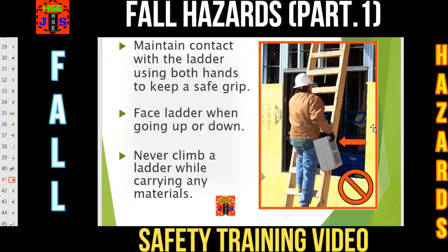Face the ladder when going up or down. Never climb a ladder while carrying any materials. Have a look. This person is going to make access on the ladder and he is taking a block in his right hand and he's going to climb up the ladder with one hand.